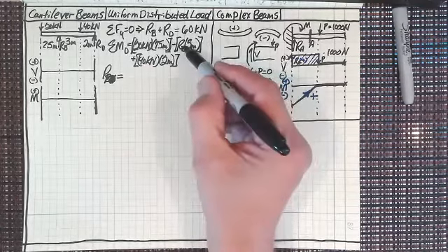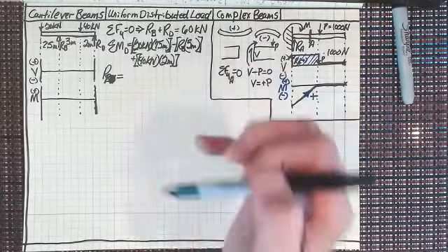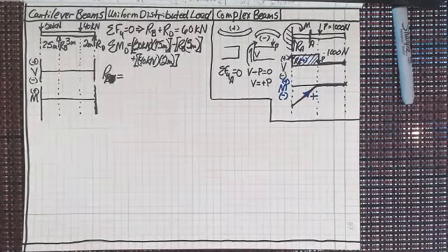So R sub B is going to be equal to 20 times 7.5. Excuse me, and I'm working in kilonewtons here, so I'm going to actually use kilonewtons in my calculations. I know you're thinking, well, it's taking you a long time. You got to punch in 3 more zeros there or whatever, right? Times 7.5. No, that's the way you do it. Or you put in 20 times 10 to the 3. You want to work in newtons whenever you work with your calculator. Your calculator hates you, right? So if you try to screw with it, it will be bad. So plus 40 kilonewtons times 2 meters. All right.